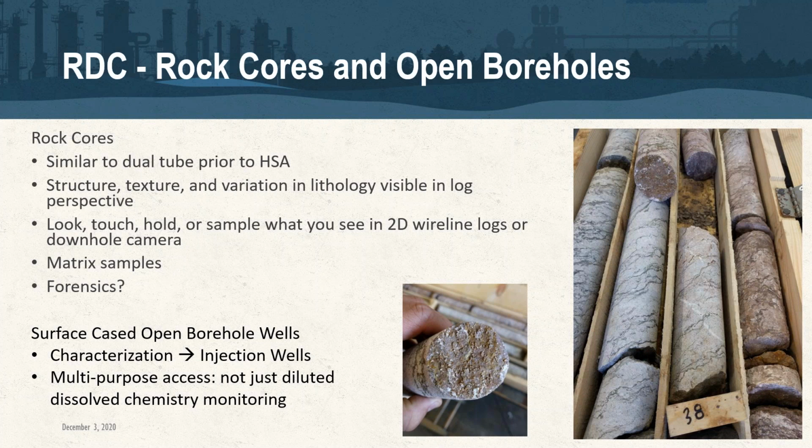and being able to do some sort of forensics on the chemistry of some of the anthropogenic effects on that matrix material itself. And so, for the purposes of our characterization and ultimately remediation, the methodology or the type of construction that we would like to have for the wells within the consolidated geology is to have surface cased open borehole wells. And the benefit of these is that you can use them for an extended number of characterization tools, but then ultimately they can be used for the remediation of the geology itself and the groundwater by use for our purposes for injection wells.